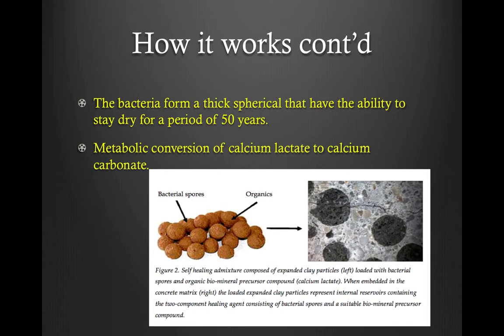How it works continued. The bacteria form a thick spherical shell that aid in the survival from chemical and mechanical stresses and have the ability to stay dry for a period of 50 years. Self-healing of the concrete via bacteria occurs through the process of metabolic conversion of calcium lactate to calcium carbonate.